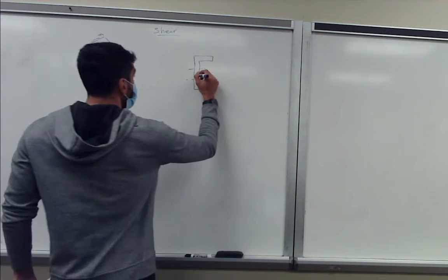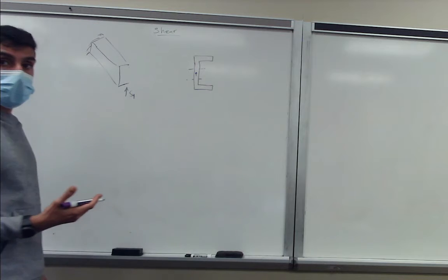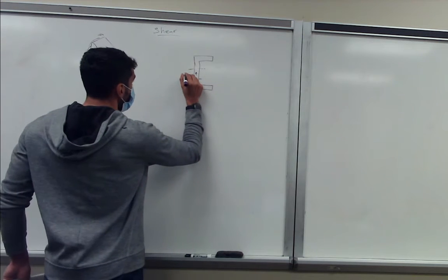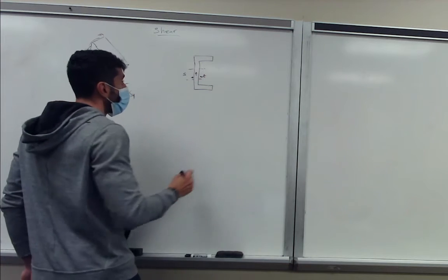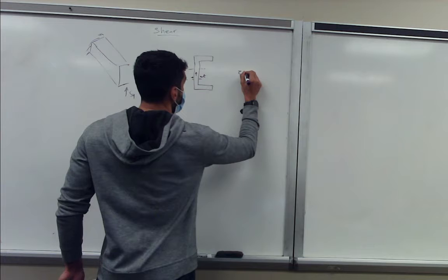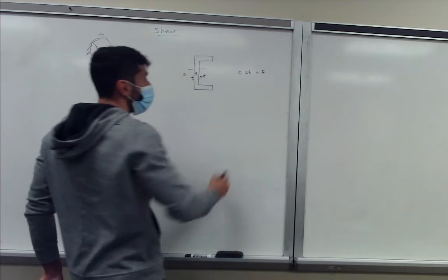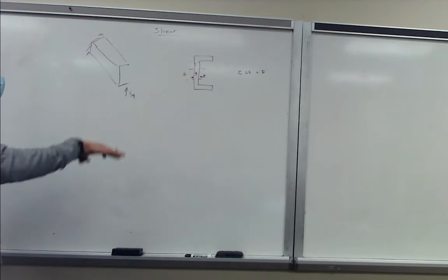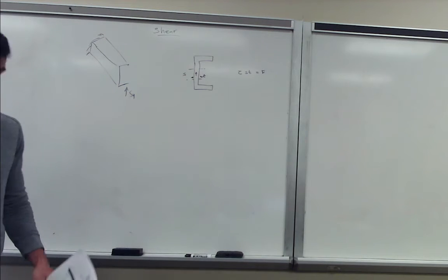We'll have a shear stress going up, and we can multiply that shear stress with our area, which is length S and thickness T, to get our shear force at that small increment. If we take the integral over the whole cross section, it should equal our external force.